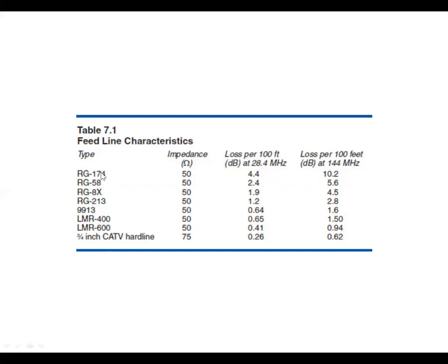keeping in mind that at the lower HF frequencies, there's not much loss. The LMR 400 wouldn't give you much benefit at, say, 160 to 20 meters in that range. I did the analysis on that once, and you start seeing the difference at 20 meters between the typical RG8 type coax and the better lower-loss coax.